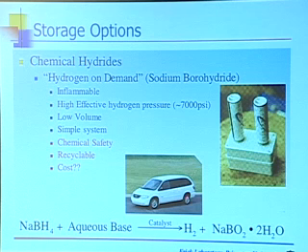And so the idea would be that you have, this is just a teeny little system, not a car-sized system, two reservoirs. One reservoir has the aqueous basic sodium borohydride solution in it. A second reservoir is going to be empty. You have a little catalyst system down here and the ability to take the hydrogen out, and you bubble the hydrogen out. Then you have this remaining solution of aqueous sodium borate that you end up pumping into this second canister over there. That's your waste from the system. It's not too bad a waste, you'll notice, that's borax. That's cleaning solution, so it's not too bad.